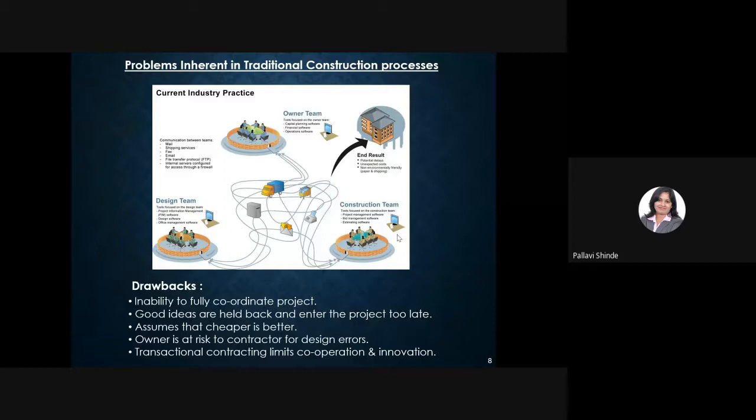Whereas I can tell you the best approach which the current construction industries are taking. So we have this BIM room meeting. So what does the BIM room meeting mean? One model is viewed by all the consultants sitting together in one room, and they are discussing these clashes, what is going wrong between which disciplines, and they are trying to resolve it then and there. This BIM room meeting is organized on maybe a weekly basis, depending on how complex the project is, or a monthly basis.